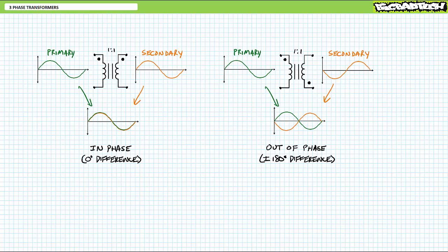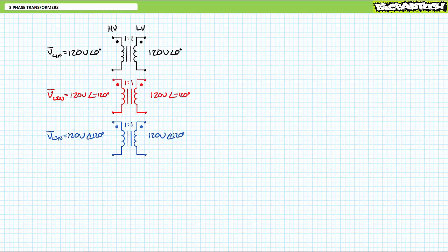Given your previous experience with single-phase AC transformers, these observations about turns ratio and phase dots should be trivial in nature. This being said, up to this point, we're acting as if we're dealing with 3 isolated independent systems and haven't hooked them up in any fashion. Since what we're about to get into can get real confusing real quick, let's ditch the step-up and step-down nature of the transformers and just use 1-to-1 isolation transformers.